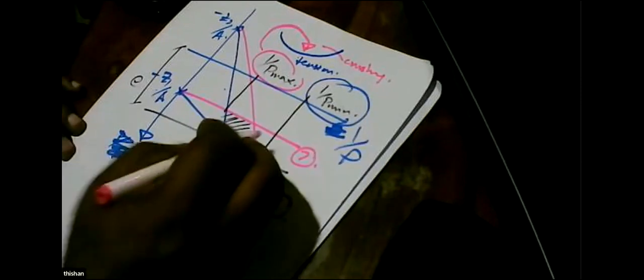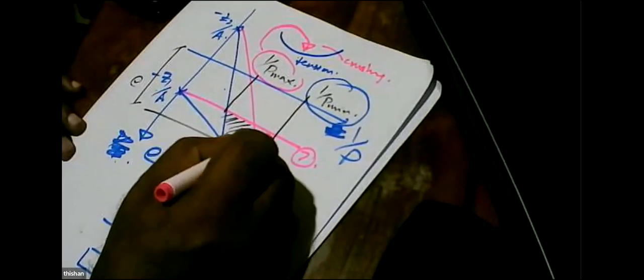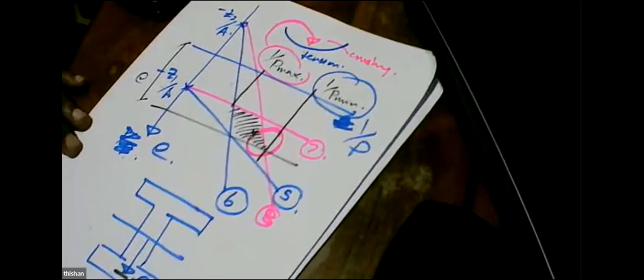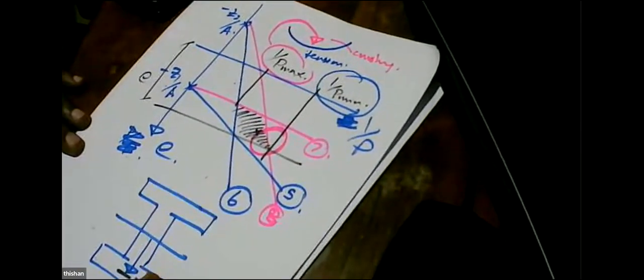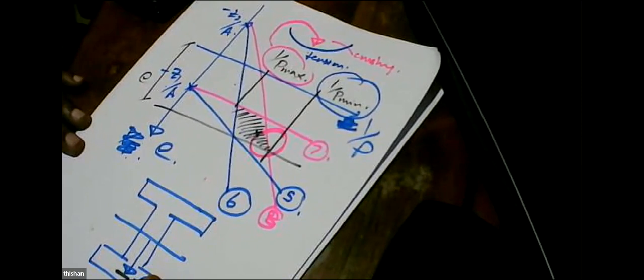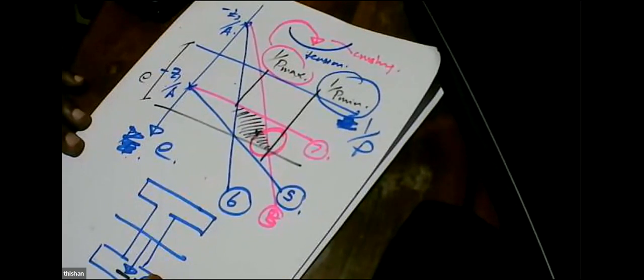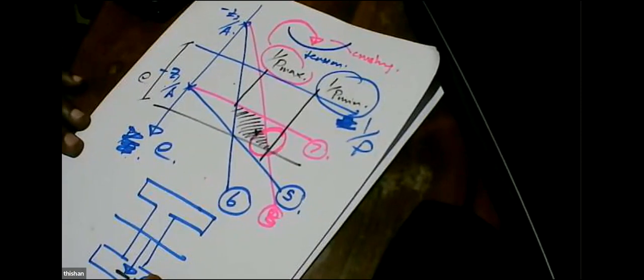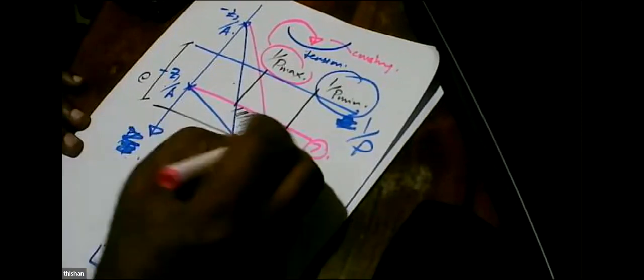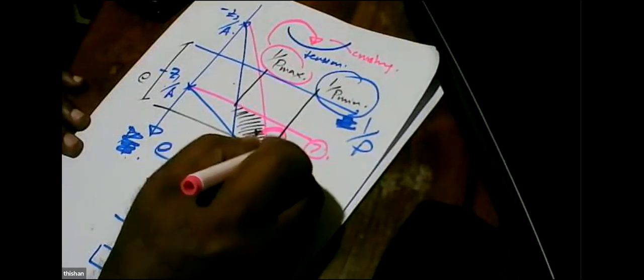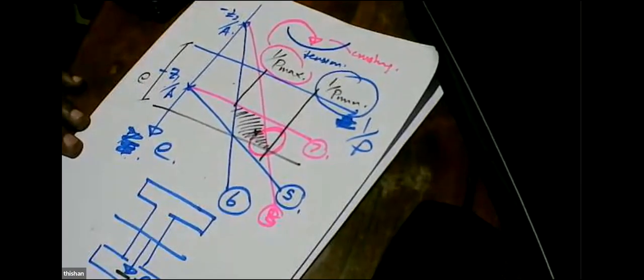So because of that reason, when you are selecting, we always like to select as close as possible to the minimum. Why? We know these pre-stressing tendons are expensive. So if you want to have an economical solution, we must always go for the minimum value given here.